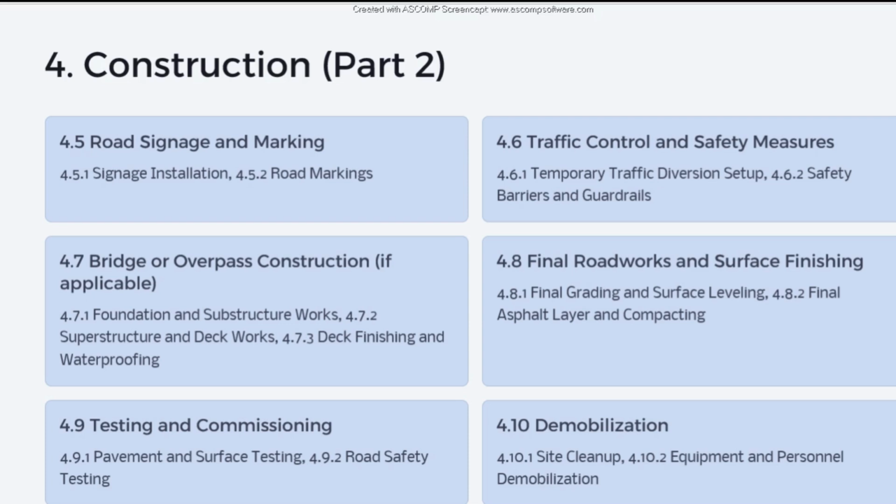So when you have another layer you can correct this difference in tolerance or difference in dimension, and you can reduce this difference between the original grading in the drawing and the implemented grading in the first layer. You can correct the difference in the thickness between the layers implemented in the first layer and the original dimensions mentioned in the drawings. This way you can correct whatever you did in your first layer in regards of grading, leveling and thickness.